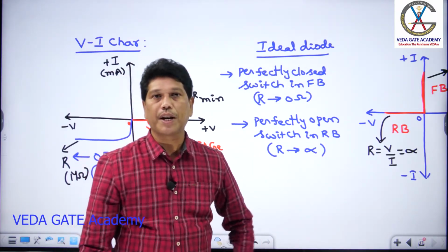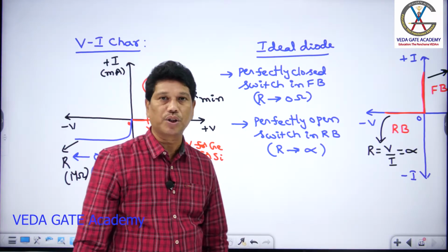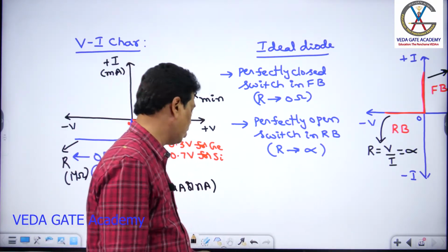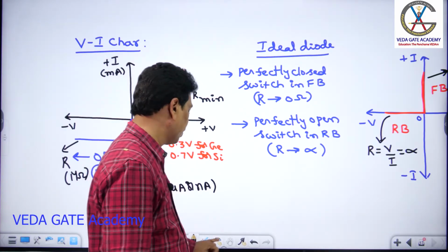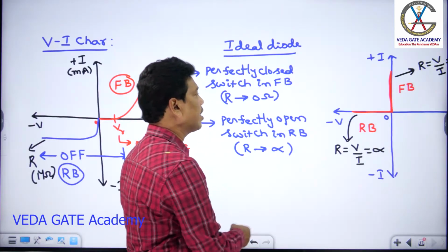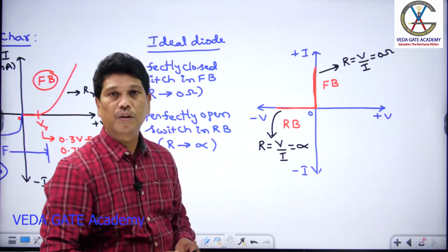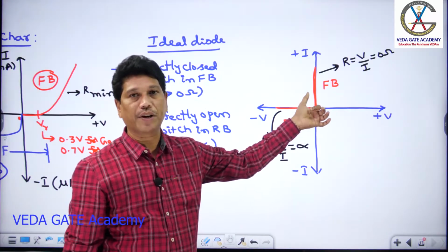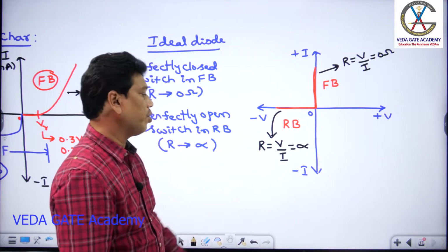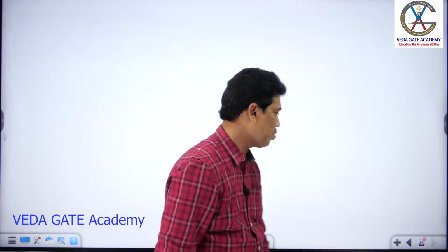So based on that, now I can examine the equivalent model of a diode, both for ideal condition and practical condition. For ideal condition, the diode resistance is unlimited and the barrier effect is 0, as I told. For a practical condition, the barrier effect is there, and the diode resistance must be limited. The ideal one is only theoretical; practically you consider the practical diode. This ideal approach has barrier effect 0 and diode resistance unlimited. Now I can discuss the equivalent models of the diode, both for ideal and practical condition.